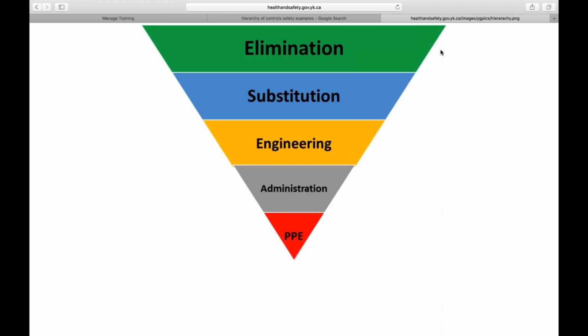So pre-bid planning, planning safety into that job, is just as important as planning materials and the work practices and how we're going to get jobs done. Nowadays you're starting to see more and more that pre-planning for safety is coming into account. How many fire extinguishers will we need? Do we need a fire brigade on this facility? Are there any significant risks of fires, struck-by or fall hazards, excavation hazards, or above ground or underground utilities that we need to be concerned about? All that will come into play.